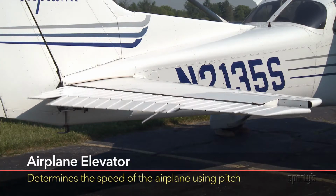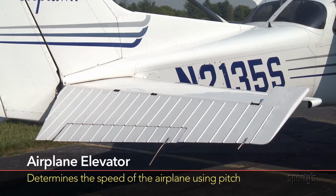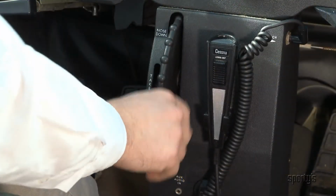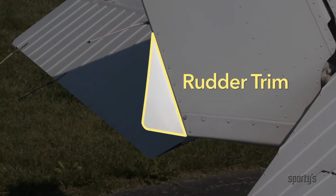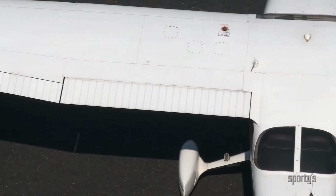The position of the elevator determines the speed of the airplane, and the elevator trim is used to maintain a constant speed, not a constant pitch. Elevator trim can be adjusted in flight, but on most training aircraft, rudder trim can only be adjusted on the ground.